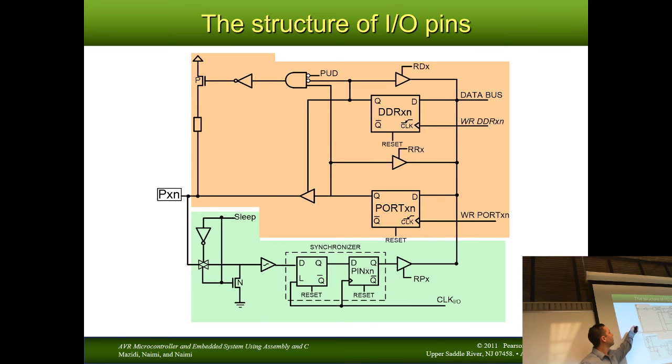Unless this thing, this is a MOSFET or some kind of a FET. I don't know exactly how it's implemented, but for now we'll just call it a FET. If you put a 1 here, we'll be connected to 5 volts. If you put a 0, it'll be an open. So let's follow that back for a second. Goes through an inverter, goes through this magical AND gate. Now these 2 signals are control signals from elsewhere. Specifically, we care about if the data direction pin is 0.